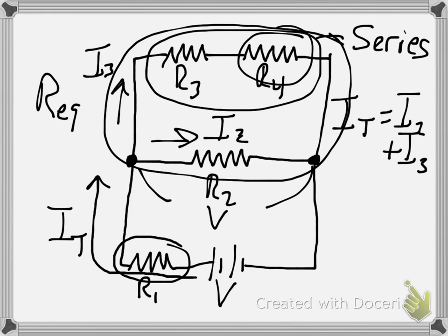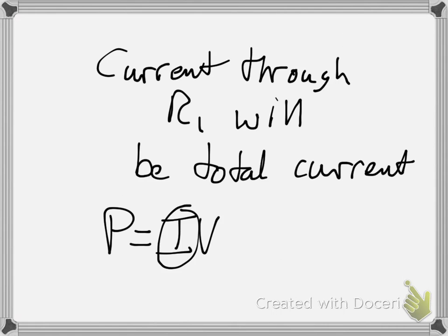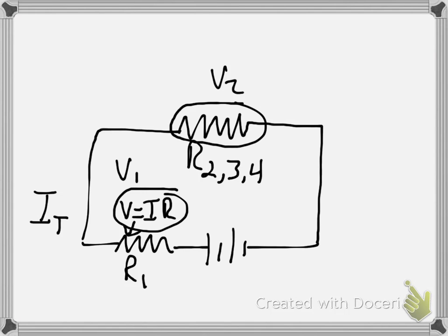And so then you can work backwards a little bit and apply Ohm's law as necessary to get the current through each resistor. And then once you have the current through each resistor, you know the voltage across each resistor, you can then calculate the power. Alright? Okay.